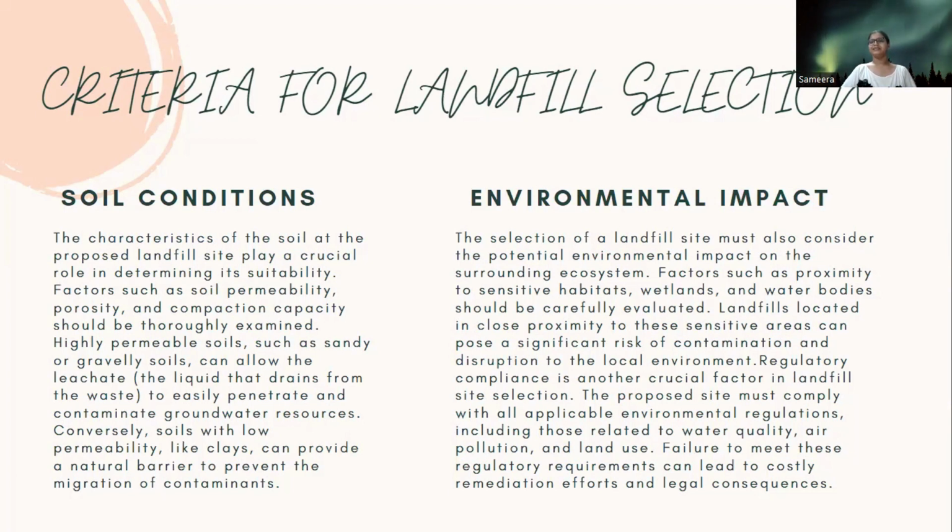Environmental impact. The selection of a landfill site must also consider the potential environmental impact on the surrounding ecosystem. Factors such as proximity to sensitive habitats, wetlands, and water bodies should be carefully evaluated. Landfills located in close proximity to these sensitive areas can pose a significant risk of contamination and disruption to the local environment.